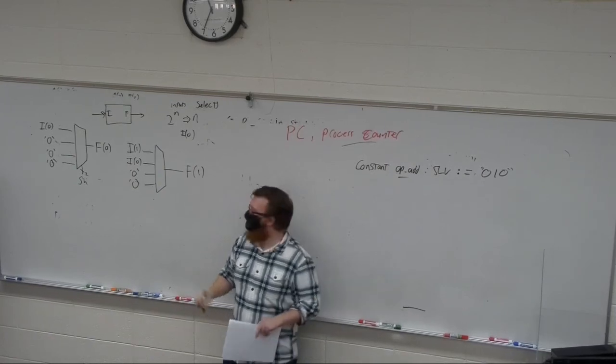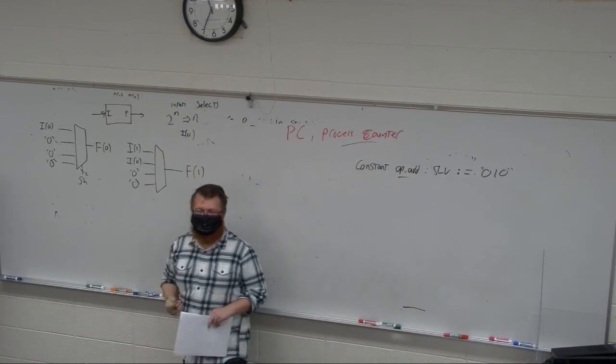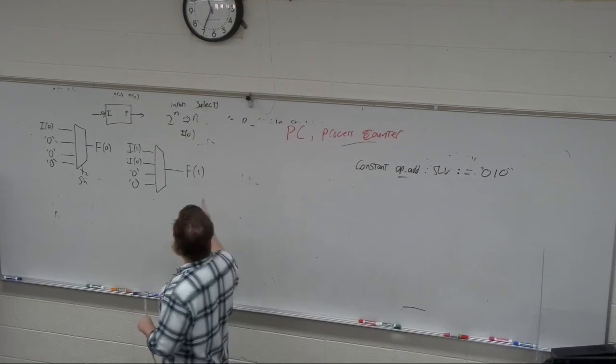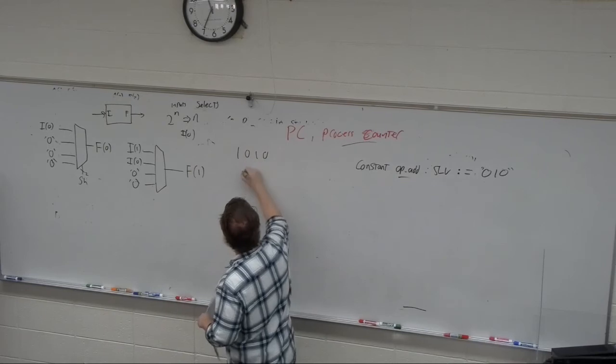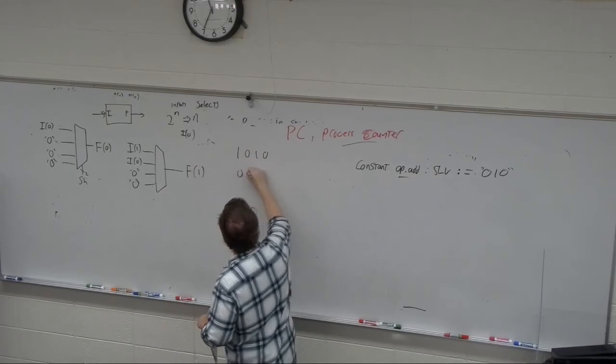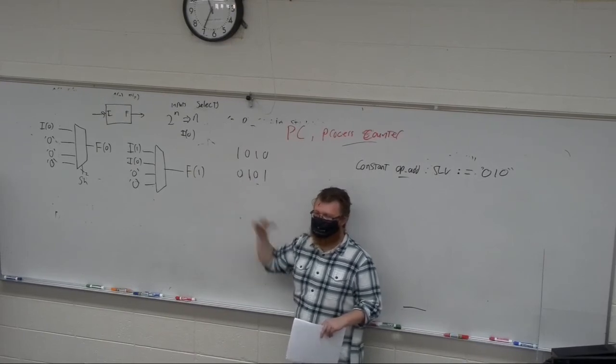And I just repeat that, getting fewer and fewer zeros and more of the inputs. Let's take it a step further. What happens if I want to barrel shift, meaning it wraps around? So my barrel shift, one barrel shift left, does that.